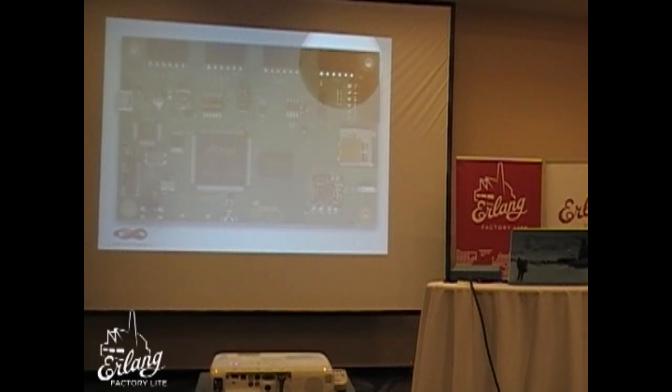So one normal SPI port. SPI is kind of like GPIO, general purpose I/O, but it's a serial connection, so you can chain things up and attach even more things to this. And we have an extended SPI port, which has a double set of connectors with interrupts as well. So you can have a device that sends you an interrupt, and then you can go and fetch more data when something has been read or when the device is ready.